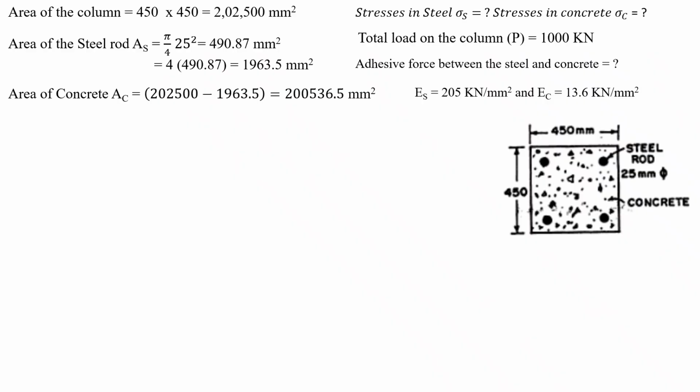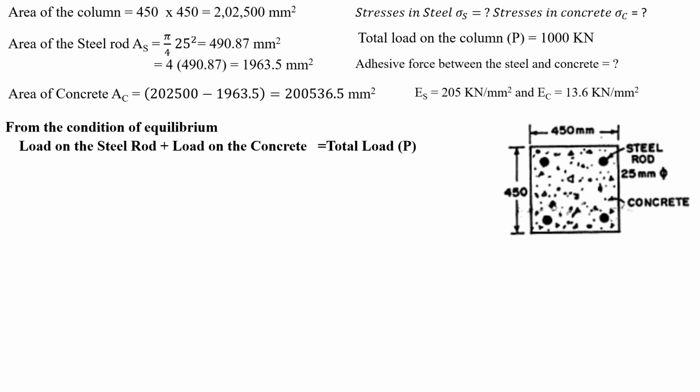First we determine the stresses in steel and the stresses in concrete. We know that while solving compound bar problems, we use two relations. One is the condition of equilibrium. The second one is the equation of compatibility. Let's see the first one, the condition of equilibrium.